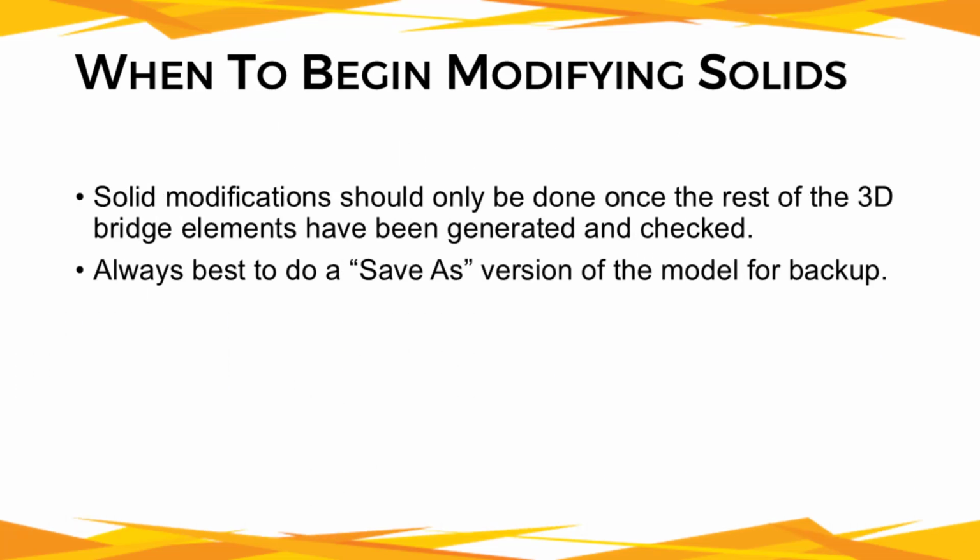Solid modifications should only be done once the rest of the 3D bridge elements have been generated and checked. Oftentimes, making changes to the model's elements with the MicroStation 3D modeling tools can make those elements unable to be altered with the OBM bridge modeling tools after the fact. We highly recommend doing a save as version of the model for backup. One pre-solids mods and one post-solids mods would be extremely helpful